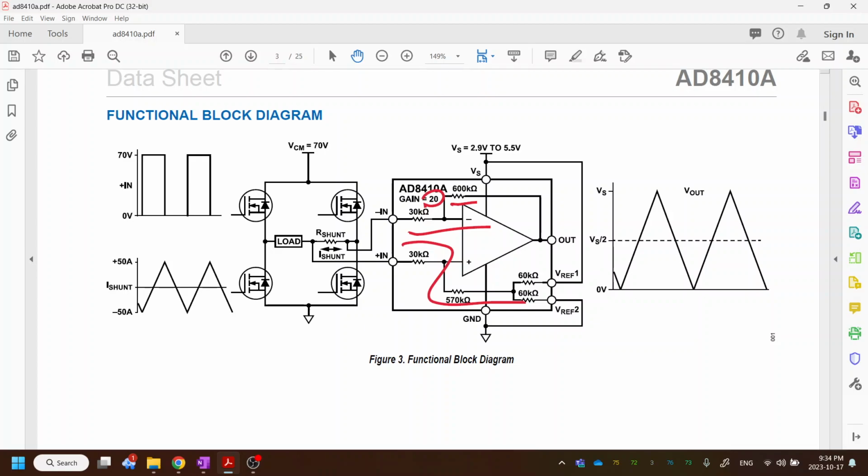And how it works is you have a current flow through a small value current shunt resistor and produce a small voltage here. And the amplifier will take the difference voltage between these two sides and amplify it. And so you will know the current going through this circuitry here. It's an H bridge. And of course, they have many other functions for higher accuracy.